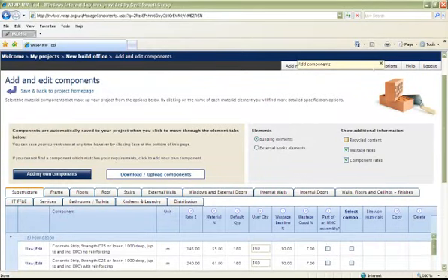You now need to go through each tab selecting the building materials which are applicable to your scheme. You should select as many as possible as you can delete items later. Remember, you're trying to estimate waste, therefore focus on the components most likely to produce waste. Some components will match your specification closely, others may need editing to match your specification.